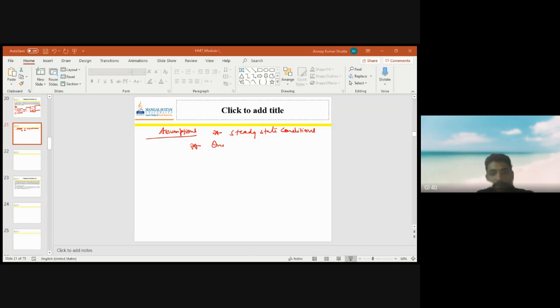Now another problem based on the Fourier law of heat conduction. To determine the thermal conductivity of hydrogen, a hollow tube with a heating wire concentric to the tube is often used. Essentially, the gas between the wire and the wall is a hollow cylinder, and an electric current passes through the wire. So this is the method by which the conductivity of any gas is measured. These are the parameters given during the experiment, and we need to calculate the thermal conductivity.